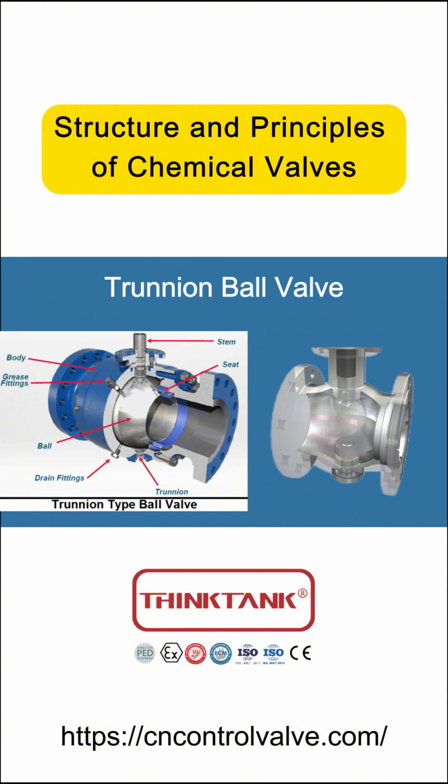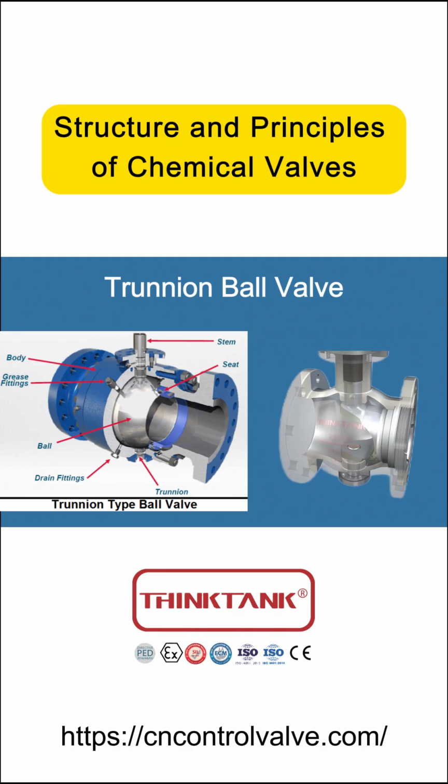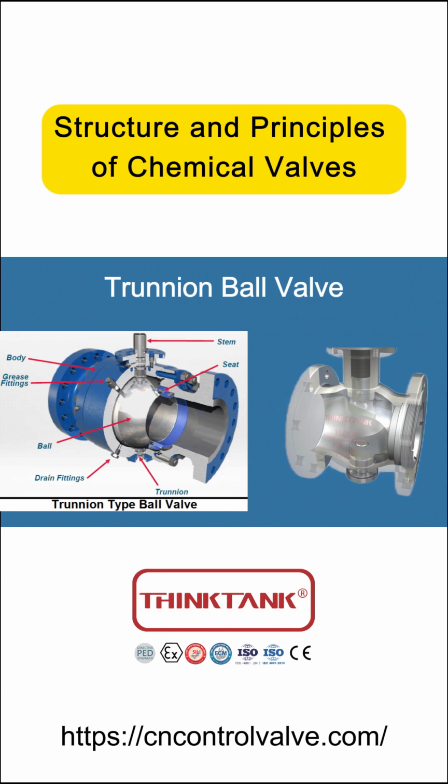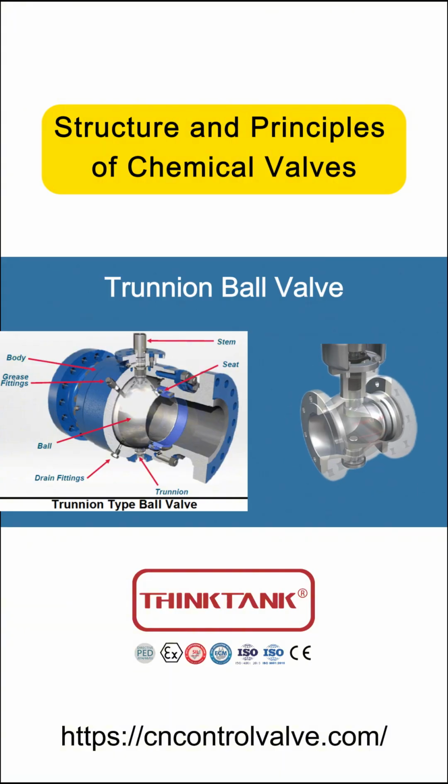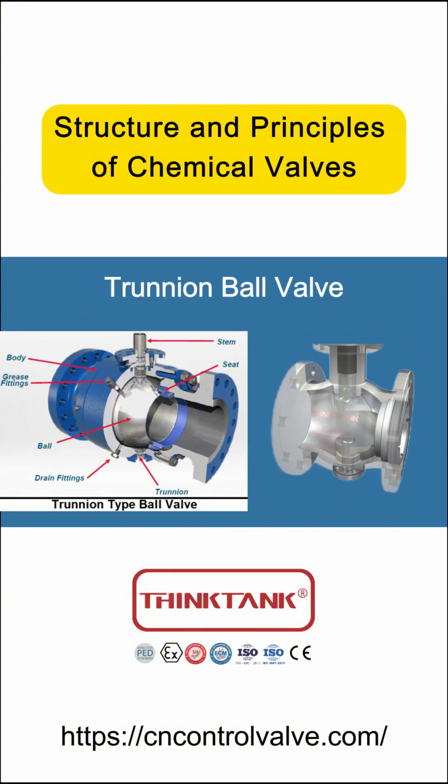Floating ball valves are generally used for pipelines up to DN 200 in low to medium pressure applications. For high pressure, large diameter pipelines, a trunnion-mounted ball valve would be selected. Although ball valves can provide some flow regulation during use, it is generally not recommended to use standard ball valves for regulating flow. Keeping a ball valve in a partially open state for an extended period will greatly reduce its service life. The impact of the media will damage the edge of the ball's bore and the valve seat's sealing surface, causing internal leakage.